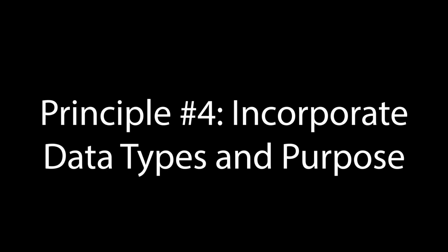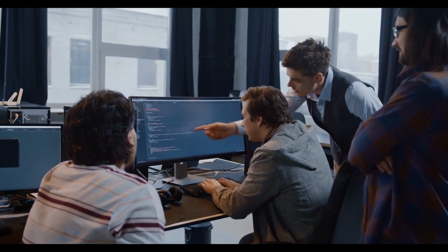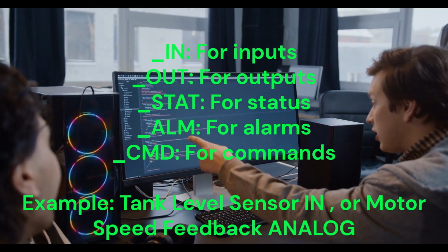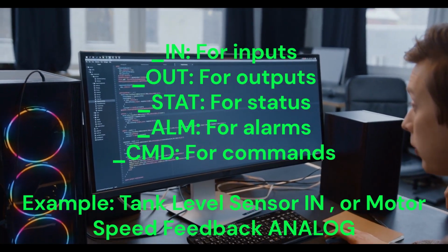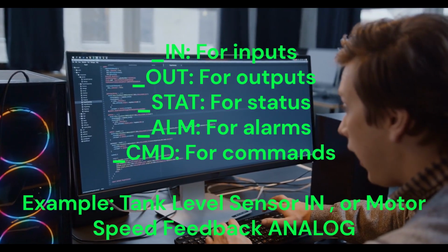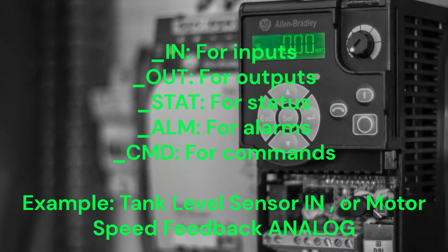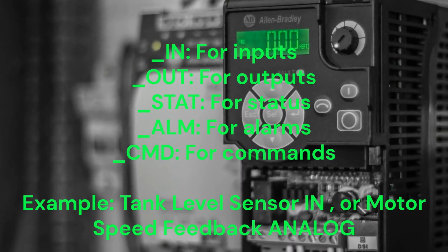4. Incorporate data types and purpose. Include a prefix or suffix that indicates the data type or the tag's purpose. This immediately tells a programmer how the tag is being used. Common prefixes and suffixes: in for inputs, out for outputs, stat for status, ALM for alarms, and CMD for commands. Example: tank level sensor in, or motor speed feedback analog.